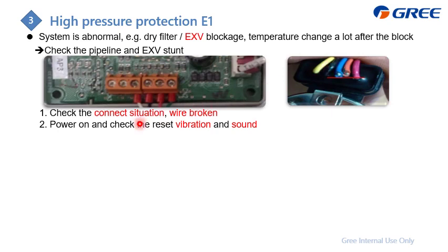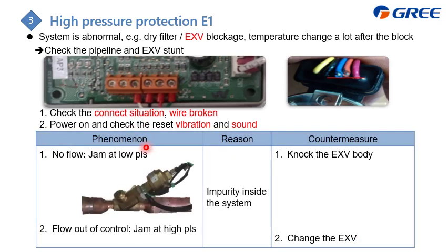And also you can reset the power of the whole system to check the EXV vibration, and you will hear tuck tuck tuck. That means the coil can drive the inside pin. If it is stuck, there are two phenomena. One is almost no flow. That means the jam happens when the pin inside is at low pulse, and at that time the impurity jams the flow.